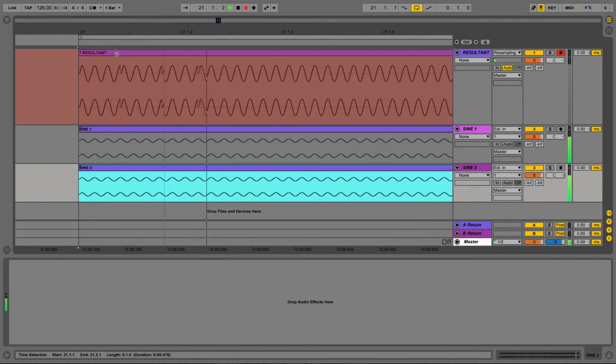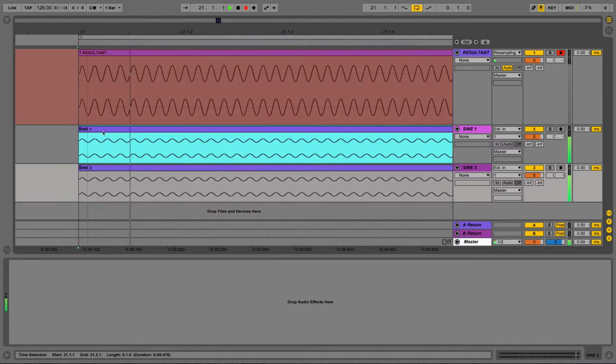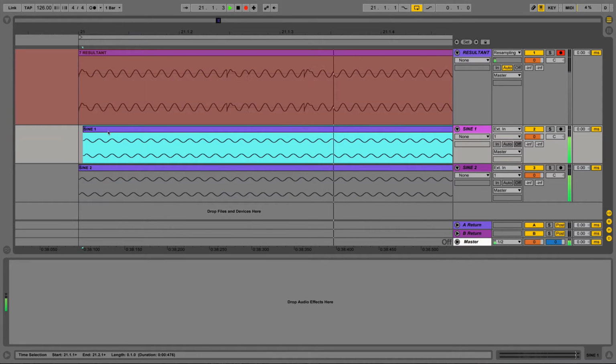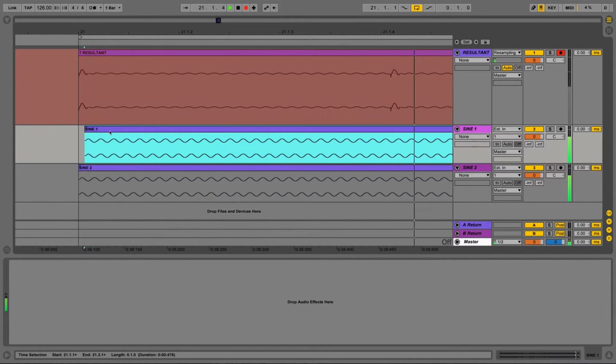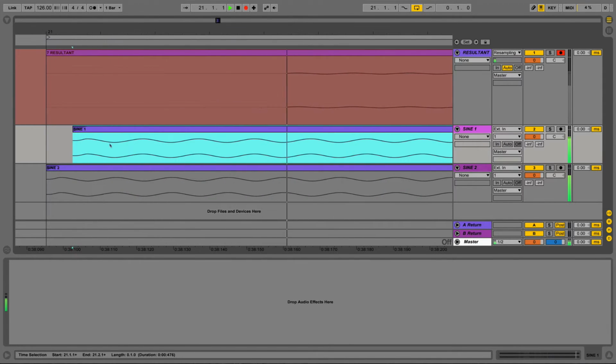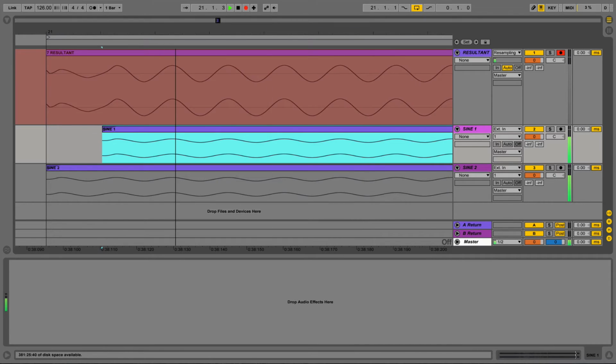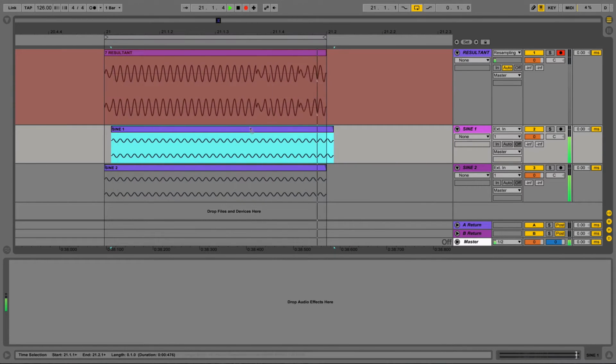And we'll notice that when we get to certain positions, when this is directly out of phase with this, then we're not going to get any sound. So if I just show you. Okay, so that's pretty much at anti-phase now. And then as we go back even further, about there, we go back through to normal phase again. So we get a sum again. And that is phasing.